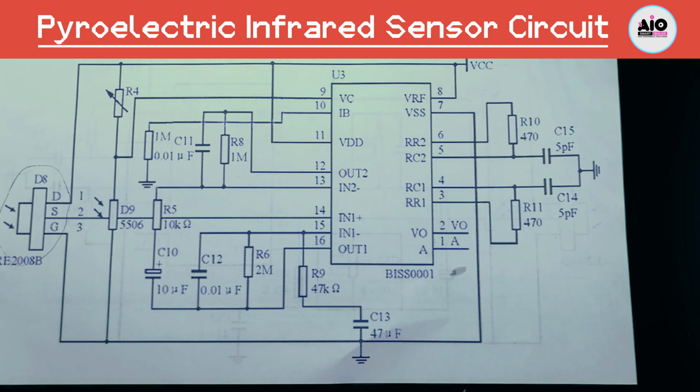Inside the sensor, there are usually two crystals with this kind of thermal electric effect, connected in series and parallel. When the external object is stationary or only background infrared radiation enters, the thermal electric effect of these two crystals will be opposite. They cancel each other out, so the change in the voltage signal it outputs at this time is relatively weak.